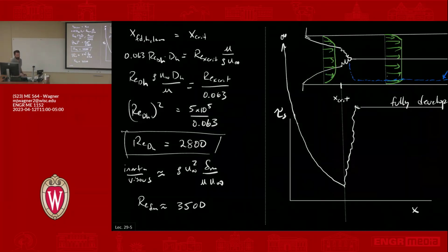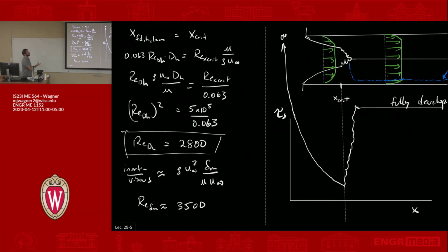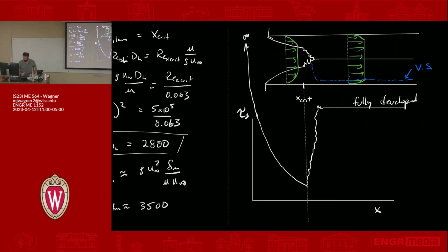All right, so we've done this conceptual stuff. Let's go in and do, because it's internal flow and we care about how the flow develops and changes as you flow along the pipe in a thermal setting or shear stress setting, we probably want to do some kind of formal analysis around this, like we've done with other things. Next page, let's do a momentum balance on this so that we can look at how we'd model pressure drop and things like that.